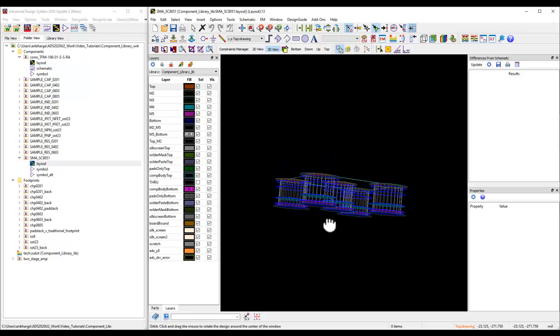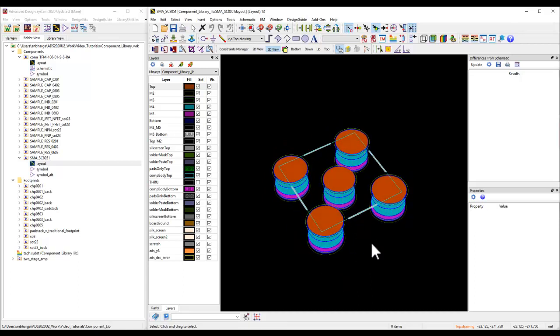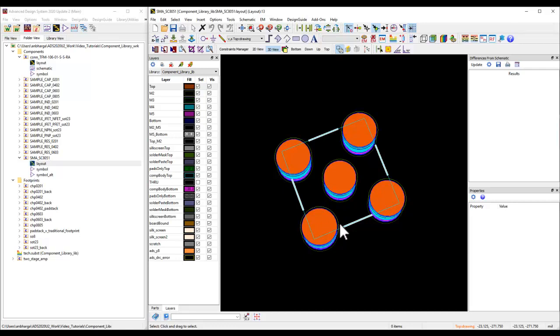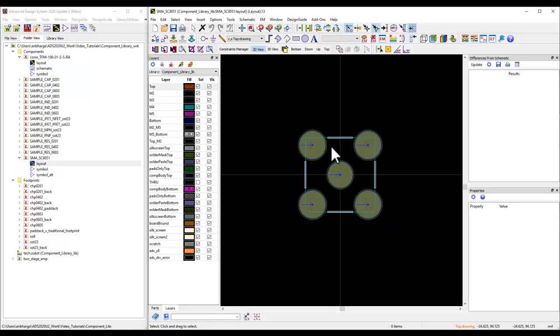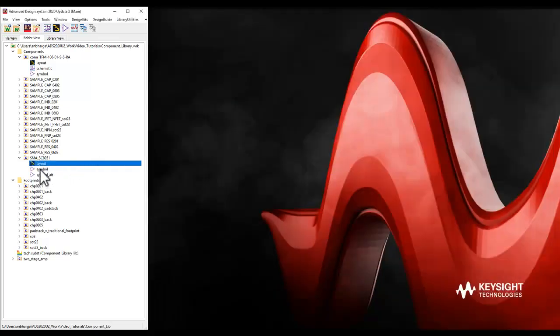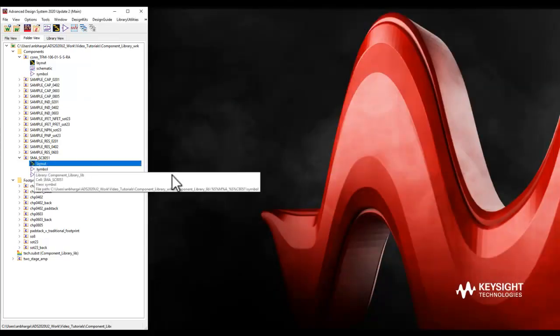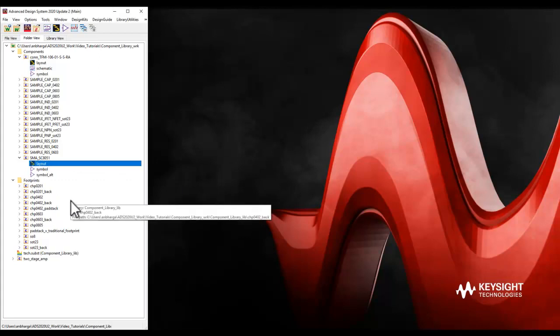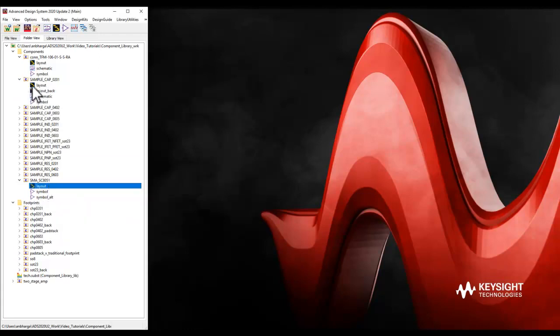Basically, these are the same pad stacks, and you can create a separate pad stack for SMA connectors. You can notice the pins you have placed on those vias. Now also, because this is an SMA for our board design, you may want to keep it at the input side or at the output side. Like we created multiple layouts before for capacitors, you have layout, layout back, and so on.